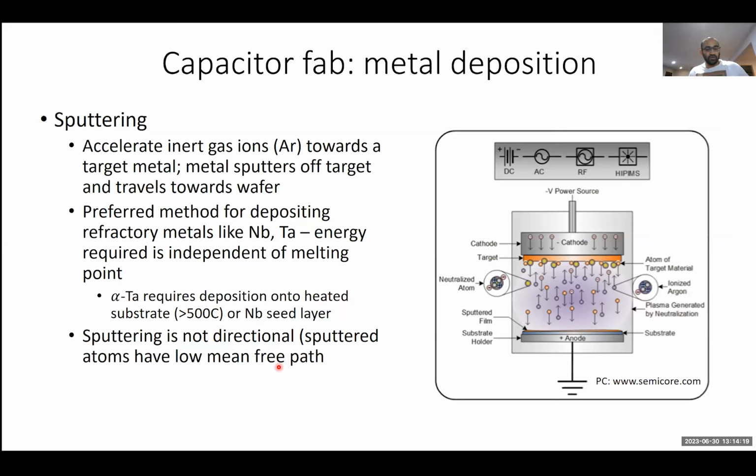You can do that. Just making a junction using a sputtering process, at least in the more standard way, using double angle deposition, which I'm going to go into detail later on in the talk, is not really possible to do with sputtering, as far as I know. So people continue to follow up.